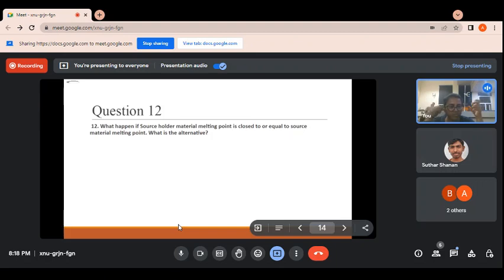That's why we are using annealing. It is a temperature treatment. Okay, so do we use annealing only for SU8 or for positive or negative photoresist also? I think it depends. If the defects are more, then in that case you can use annealing. In different processes also we can use annealing. It is only a heat temperature treatment process.